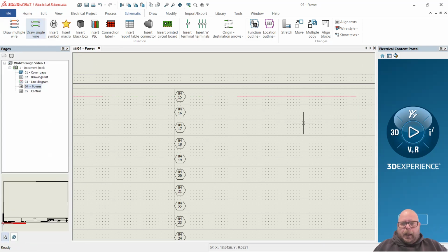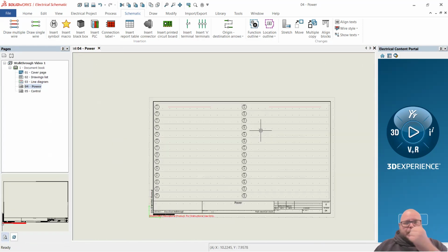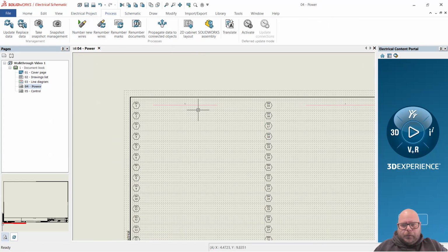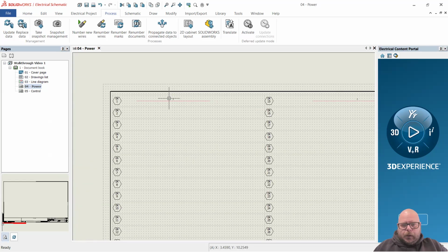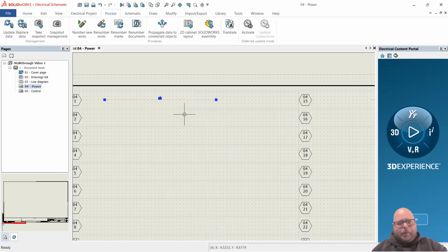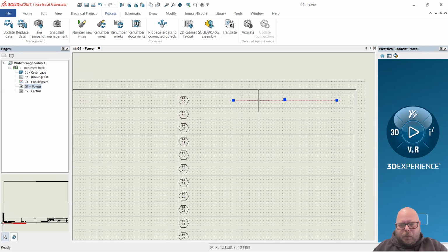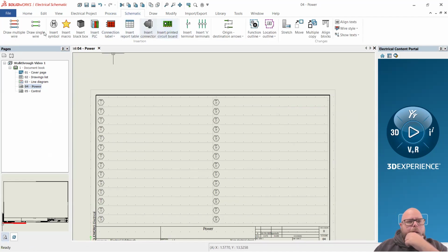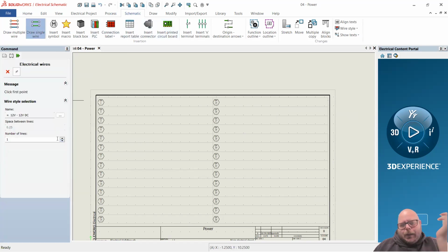And now to number these guys, that is actually up on the toolbar under project, actually process, sorry. Number new wires. Yes, I want to modify or number new wires. Okay, and that didn't work with that particular wire. This is maybe one of the things I need to jump into first. So let's go back to schematic. Again, unscripted. You got to love it, right?